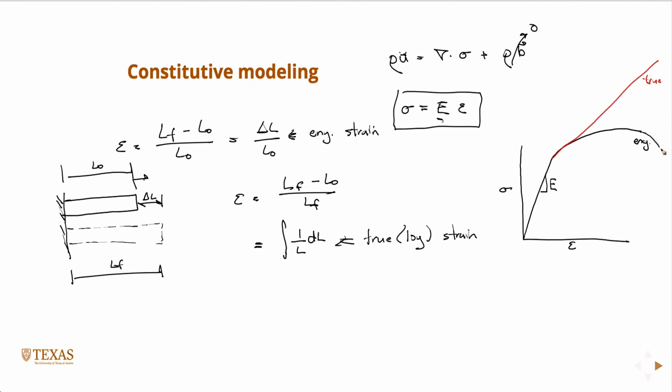specifically, if I were to continue to draw this and this were to say soften, imagine I had a little cylinder. And for the time being, let's just think of a metal, because you could probably visualize this. Okay, so I have a little pin of metal, and I'm going to pull on it. Well, at some point, that metal, if the metal's ductile enough, it's going to begin to neck. There's going to be some significant local instability, and the metal will deform like that, right? So it'll neck. This will begin to sort of suck in, right?